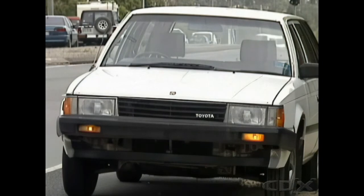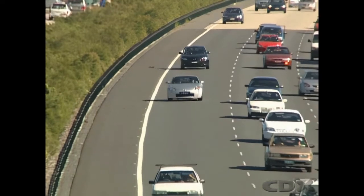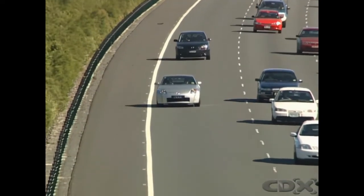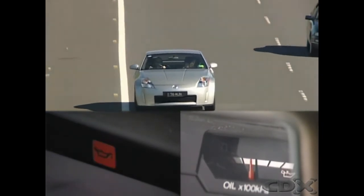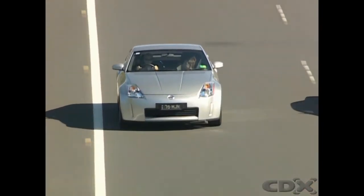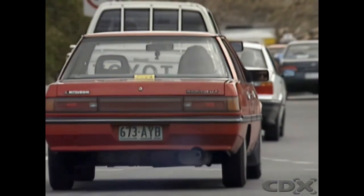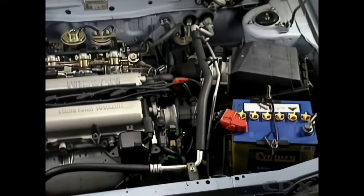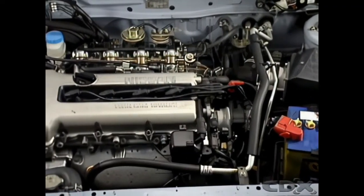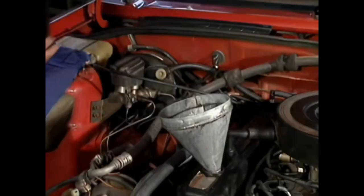If a lubrication system fails, it's serious, so it's crucial to know it's working. If oil pressure falls too low, a pressure sensor in a gallery can light up a warning light or register on a gauge. Low oil pressure can mean a lack of oil. It may have leaked away. Or it may have been burned. This can be caused by worn piston rings which let oil into the combustion chamber. Some engines even use an automatic cutout that turns off the engine if oil pressure falls too low.